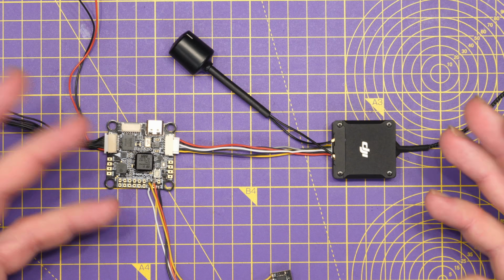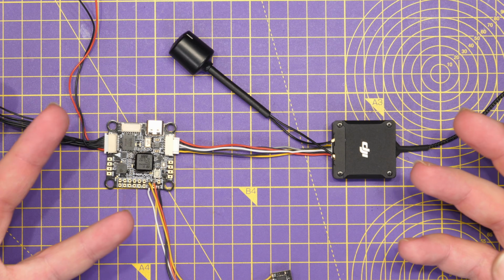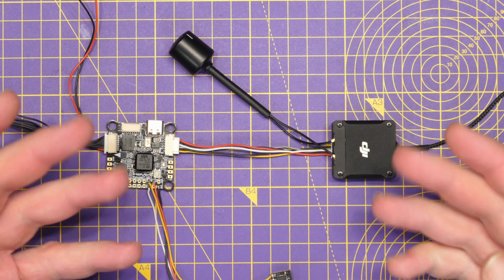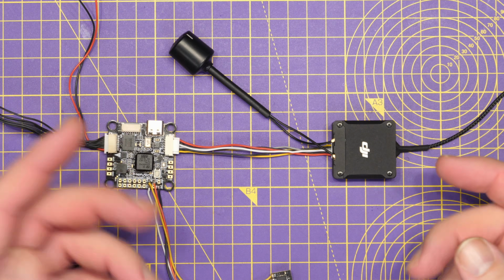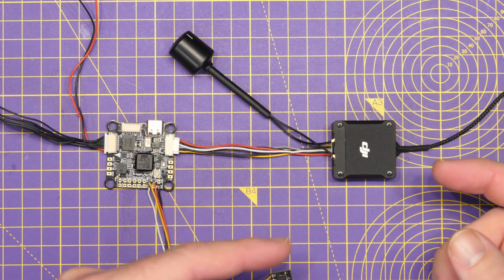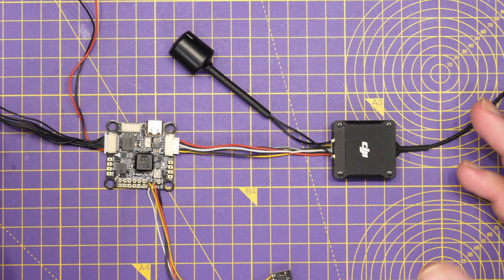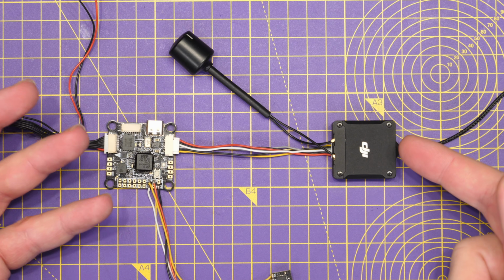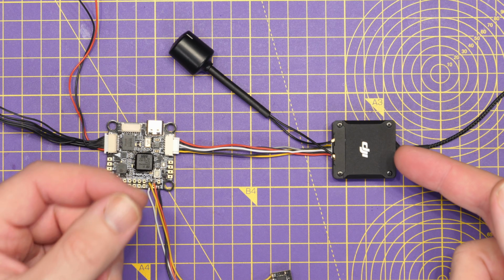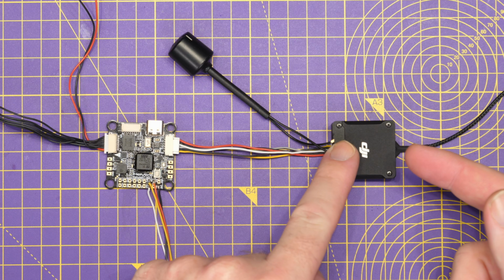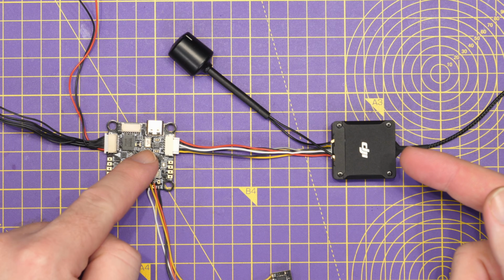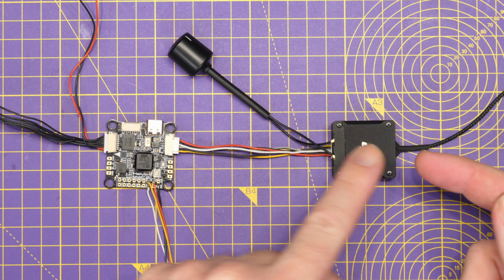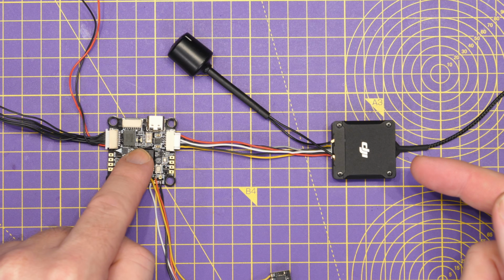Now, to get O3 working with your flight controller or Betaflight, the first thing you're obviously going to need to do is connect the two together via the physical wiring. We have power, UART, and an RC control connector. The basics are you need to connect the power, allowing the air unit to turn on, the UART, TX and RX lines, so the grey TX from the air unit to a spare RX on your flight controller, and the white RX on your air unit to a TX pad on your flight controller.